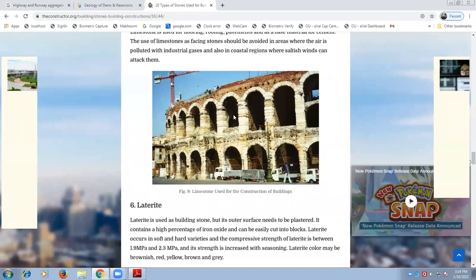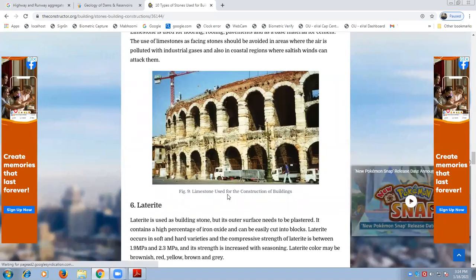First of all, these rocks should have a sufficient degree of fissility to allow them to split into thin slabs. When there is a requirement for any rock to be used in a roof, there should be a capability of these stones to split up into thin slabs. And they should be durable, long lasting, and they should be impermeable, because a roof is a structure which is constantly in touch with rainwater during rainfall, so it needs to be impermeable. Otherwise, there could be serious damage to the structure.